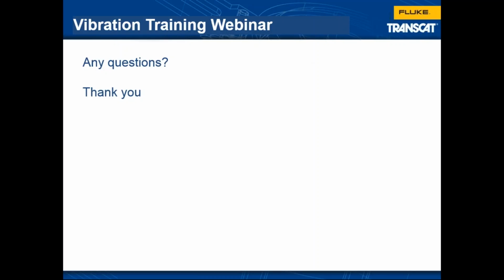Can you speak to velocity measurement versus acceleration measurement? Is the analyzer looking at acceleration? That's a good question. Actually, all three of the tools are measuring acceleration and then converting it to velocity.